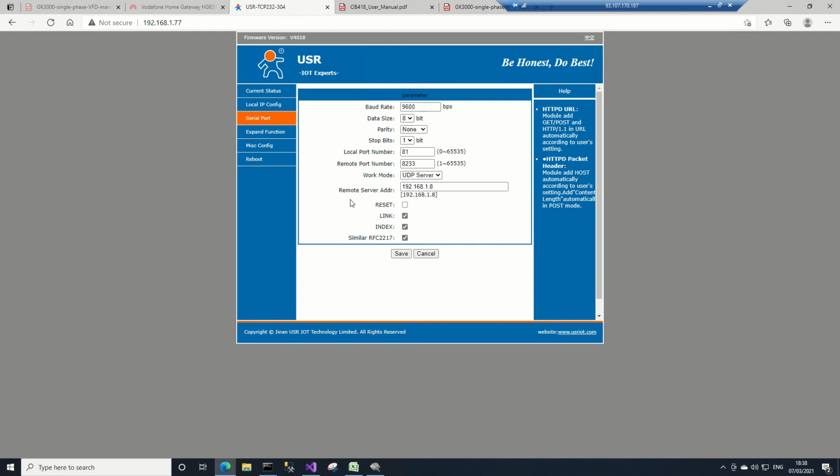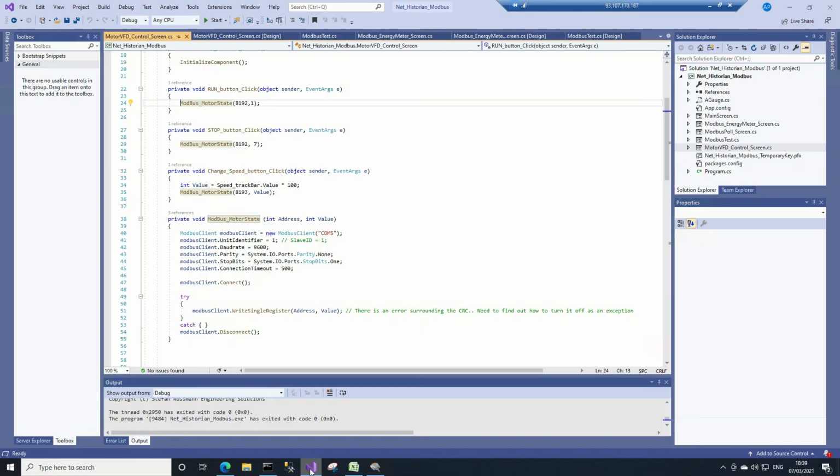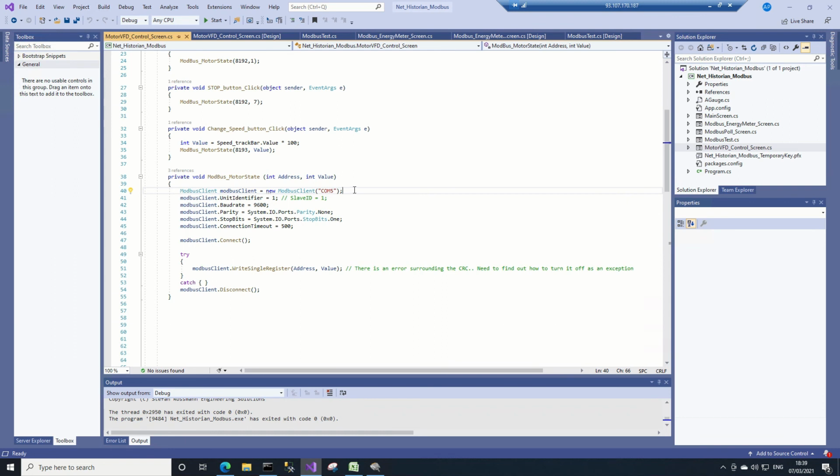So what can happen is that you have set up a circumstance where you have a virtual COM port where you can simply take the code that is relevant to the COM port send, and everything else is taken care of for you. You don't have to specify the IP address or the port of the device, and then have the conversion occur out of that area. The Modbus device over the Ethernet network actually thinks that it is connected to the PC through a COM port, and you get all of the advantages of keeping the code very, very simple.